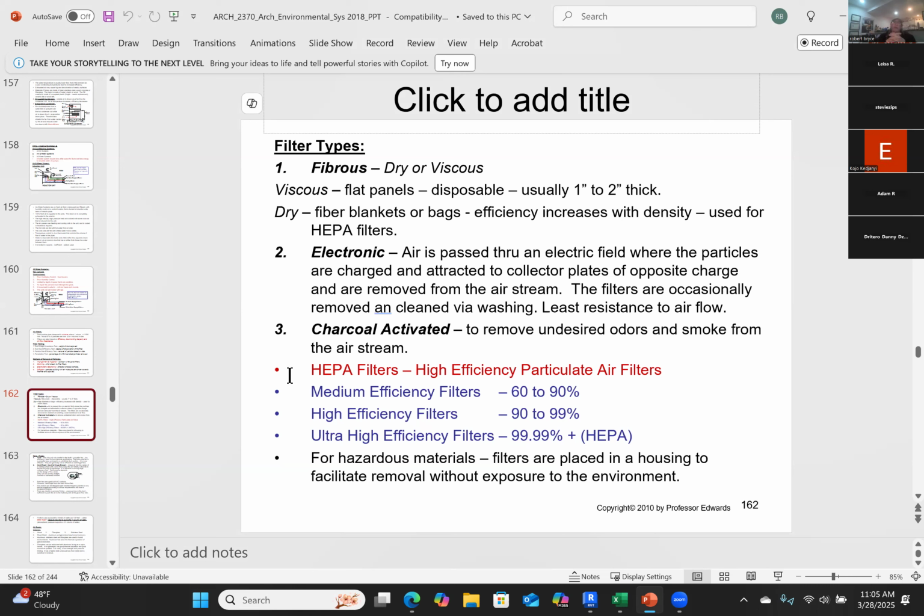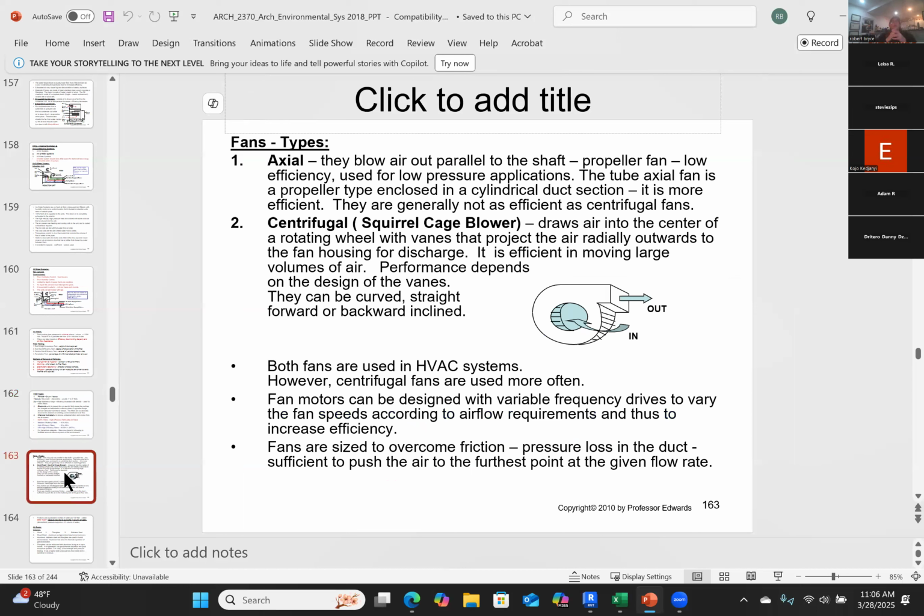And so a lot of the vacuum cleaners also talk about having the HEPA filter, but it's 99% efficient, which means that it's going to grab 99% of the particulates that come across it, which means what? That those little holes in there to begin with are going to become even smaller, which means that we're going to spend more energy to push the air through those smaller and smaller holes. So how do we move the air that we want to push through those filters?